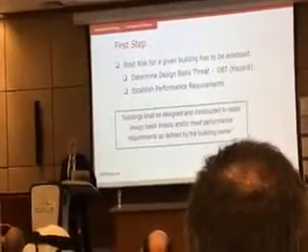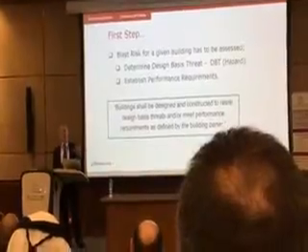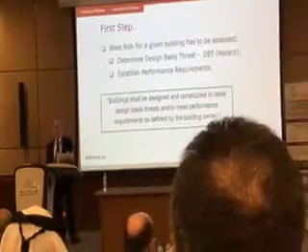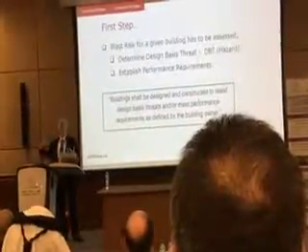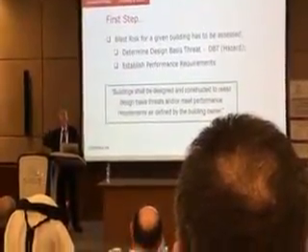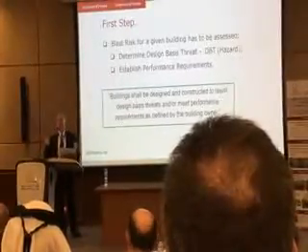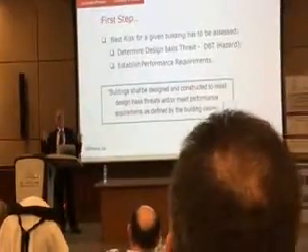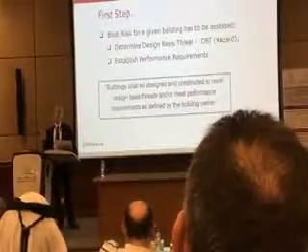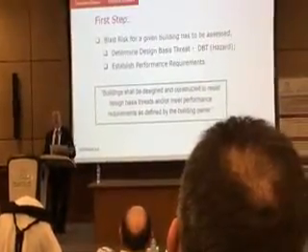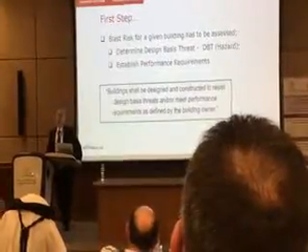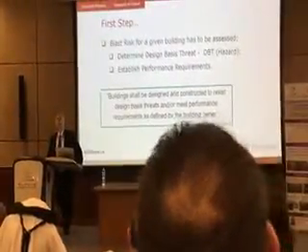So this is secret, but they eventually give you that we think that this embassy is likely to be attacked by a truck or a car, and the closest road is about 15 meters away. So these are the parameters you have to use. So given that, they gave me the charge weight and standoff distance, I immediately convert those to pressures and durations, okay?